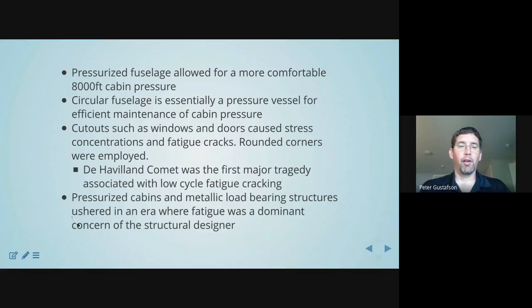There are people who climb Mount Everest without supplemental oxygen, but that's just a few and far in between relative to the human population. So by having a fuselage that can be pressurized, essentially when you're riding in a modern transport aircraft, you're riding in something where it feels like you're at about 8,000 feet, a little higher than being in Denver, around the Vail altitude, is the air pressure that you have inside the cabin.